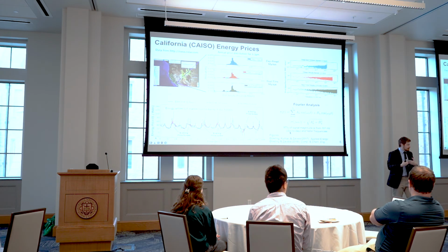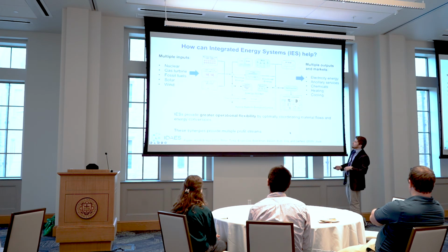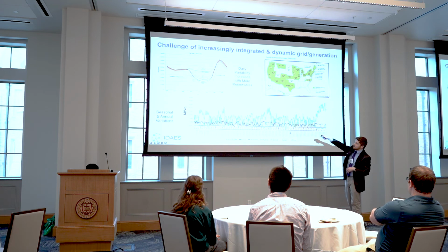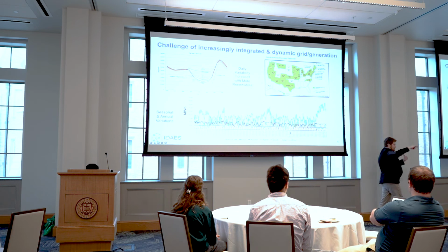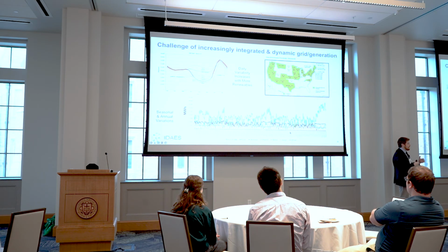So you will get scenarios where, where was the duck curve? This happens a lot on the duck curve, either when solar is coming online or going offline. You have a really big ramping event. And the change in demand is much faster than the ramping capabilities of some of the generators that are on. So you either have oversupply or undersupply. Then you will get places where the transmission constraints become active.